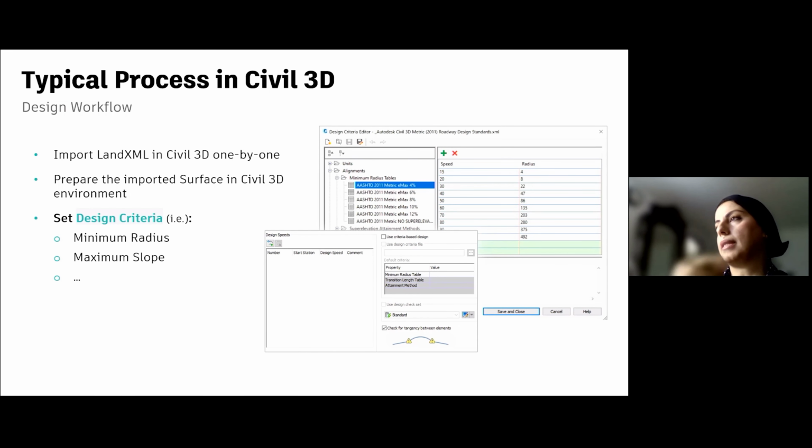Actually, before doing that, we set the design criteria. For example, wind projects are associated with special delivery requirements, because we deal with wind turbines, which sometimes go up to, let's say, 180 meters. The delivery vehicles have specific requirements, for example the turning radius and the K value.